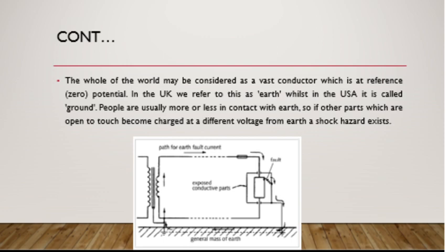It will be possible only if you have a good conductive and earthing system available for that particular location. If earthing is not available, it will not take that path, because at that time the resistance will be very high and current will not be allowed to flow. So there should be proper earthing available, to reduce the shock hazard existing at that point of time.